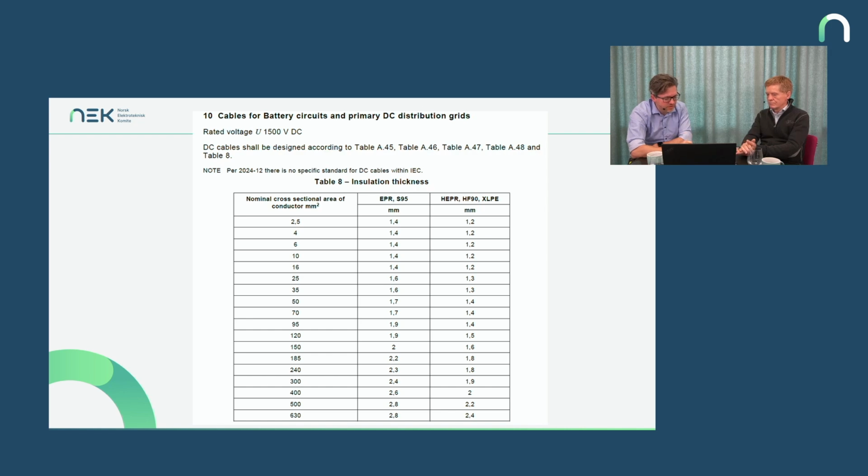They are requesting this, and as you already mentioned, the available cables that they have, using this 1.5 rule that you can come up to 900 volts, but these battery systems are often above that level. So they are requesting some other ratings. And of course, the question that many are not able to answer is, is it okay to go up to 1000 volts maybe or not, or what type of cables, etc.